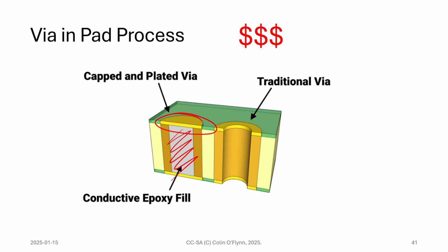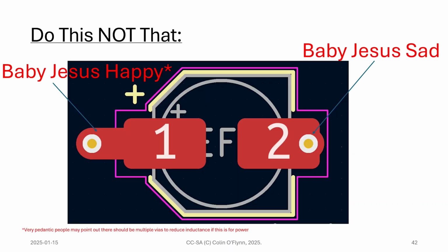So if you do a 0.2 millimeter board, and don't quote me on this, I think the fab was just giving you capped vias by default when you did the smaller via sizes anyway. Or maybe it was higher layers, something like that. So it used to be a big thing, but it's always good practice: if you don't need the space, do not do this, right? And it's very easy to do, because you might just push the via in a little bit closer, and all of a sudden you're in a via and pad. This little bit of trace here is just what you need.